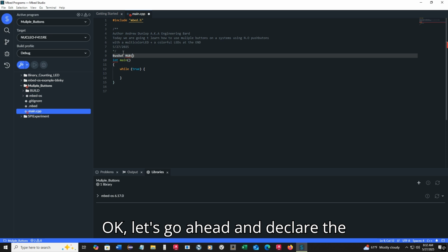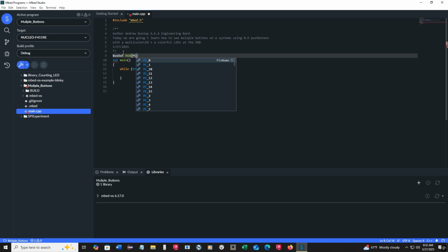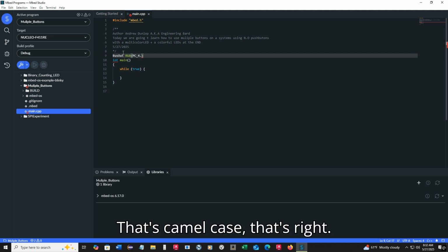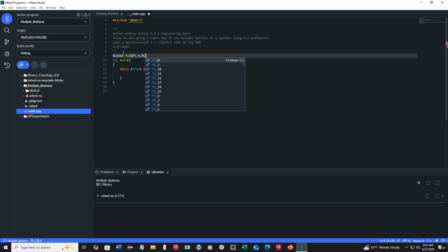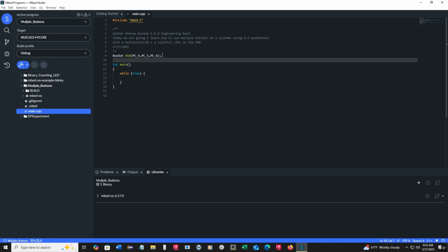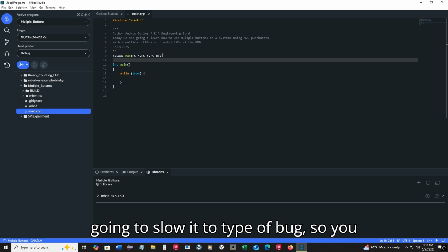Let's go ahead and declare the variables. BusOut, that's camel case, that's right. RGB, PC4, PC5, and PC6. I'm a slow typist, so you have to bear with me.